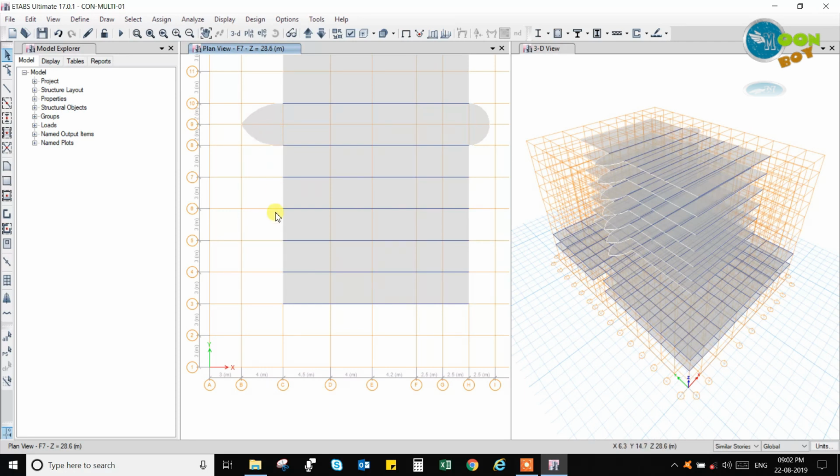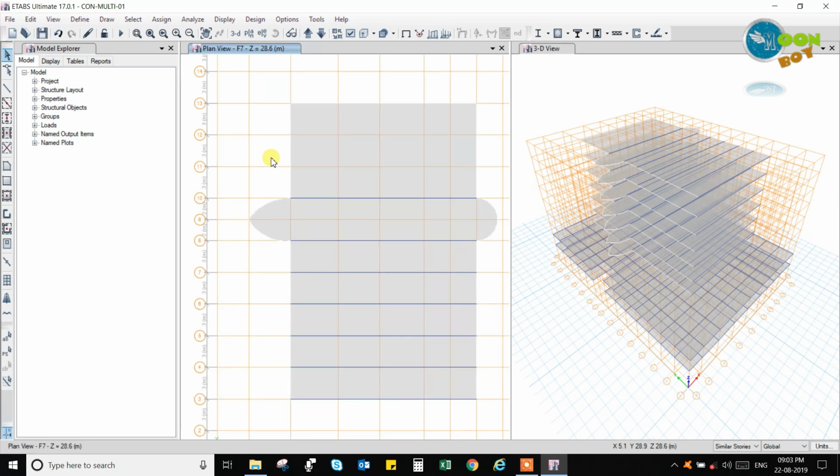So for one type of building they will use one type of plywood. If you have many buildings of similar design and similar beams, you can make that in MS plates and go for shuttering. So you need to consider all these sizes.